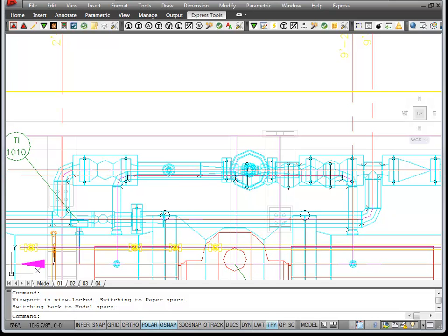Hello, this is a video to introduce you to the EDGE-iTag tools that are part of Plant EDGE. EDGE-iTag is used to place intelligent bubbles onto the drawing, and the reason they're intelligent is that there's a connection maintained between the actual 3D component and the tag, so that if any of the data inside the 3D component, such as its tag or line number or mark or assembly, changes, then also the bubble's text will also change. So that is the intelligent portion of EDGE-iTag.